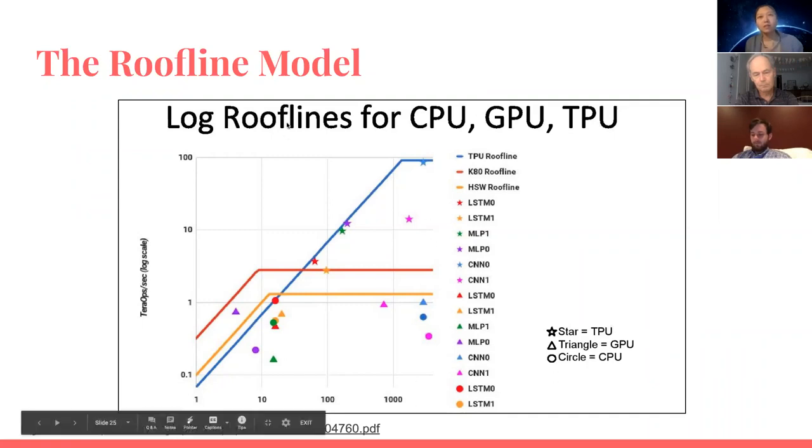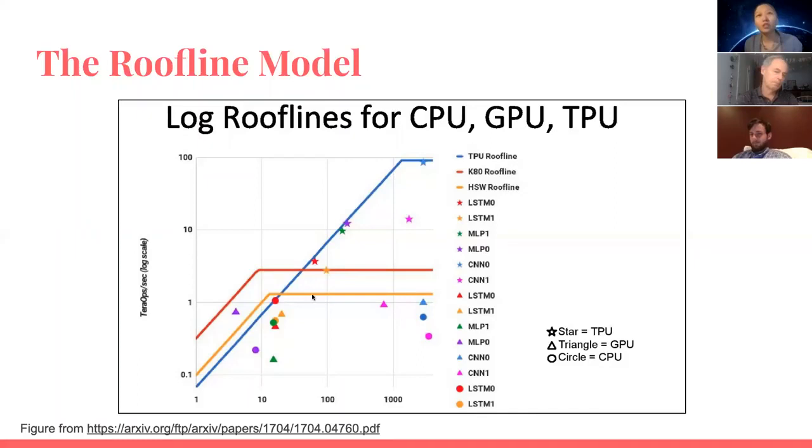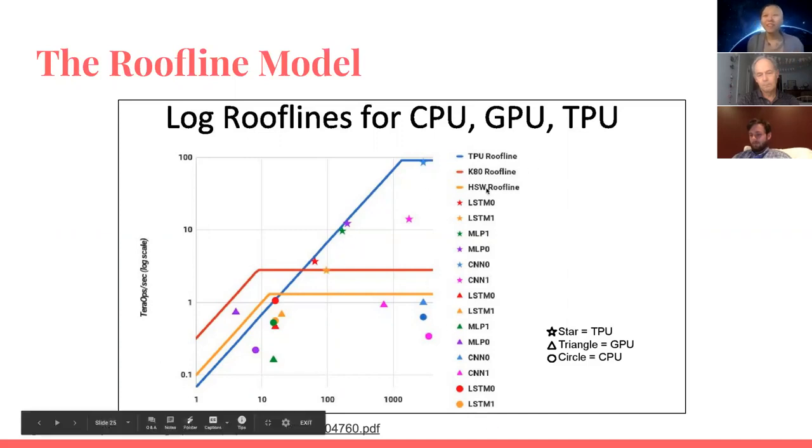So the x-axis of these workloads is determined by their own characteristic, which is the operational intensity, which is the arithmetic intensity. And then their y value, their throughput, should be determined by the roofline. If they're not strictly following the roofline, that means there is probably more space to optimize in the software. But in all these examples, they are roughly following the roofline, except for the stars, for this star, for example. But the other ones, for TPU, it's following this roofline pretty well.